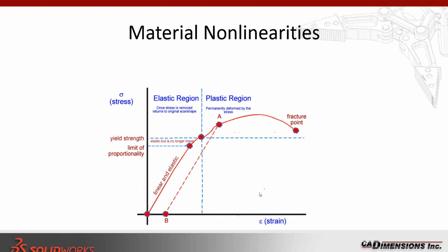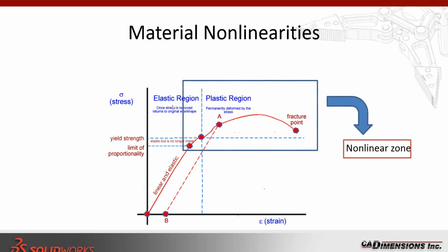All these areas is completely disregarded. In a linear analysis, what happens is this graph will just be extended in a linear form, and essentially everything past this dotted line here is garbage. It's not real value. When it comes to nonlinear analysis, this is what we call the nonlinear zone right here. So this small area right here, typically in a nonlinear analysis, it is still considered. In most cases the values are very close to the linear line that you have. However, it's still not exact.